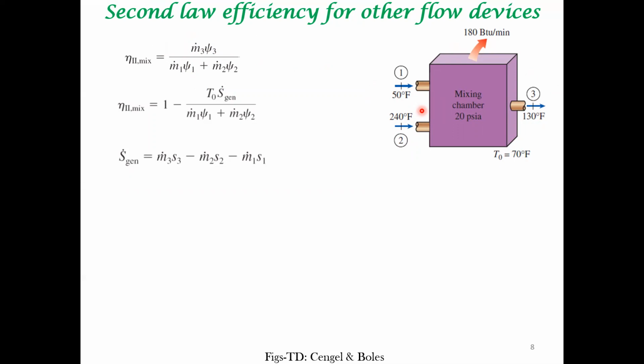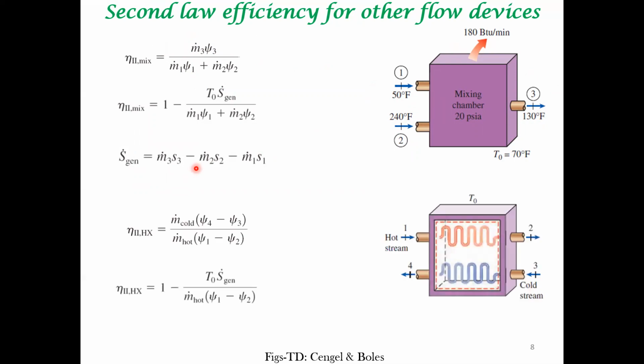And then we can get to exergy destruction, again entropy generation, by using other balances which we have seen in the previous lecture, and an entropy balance. So another case where there is inherent irreversibility is in a heat exchanger. There is always a heat exchange from a hot stream to a cold stream. That's what a heat exchanger does.